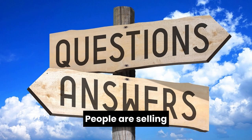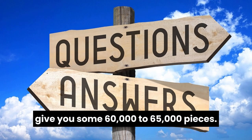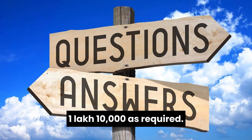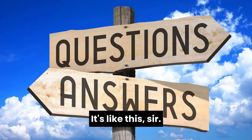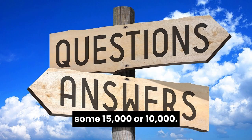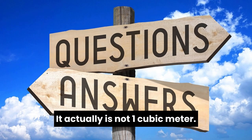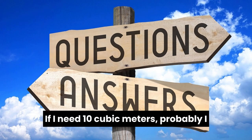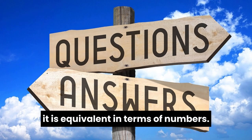Sir, people are selling this media by volume. They say 1 cubic meter, but they'll give you some 60,000 to 65,000 pieces. Nobody is giving you 1 lakh or 1 lakh 10,000 as required. So how can we ensure it is at least 1 lakh? We have to buy more. It's like this, sir: when he says something is 1 cubic meter, it actually is not 1 cubic meter, it is 0.7. With that knowledge, we should buy. If I need 10 cubic meters, probably I need to buy 15 cubic meters because it is equivalent in terms of numbers.